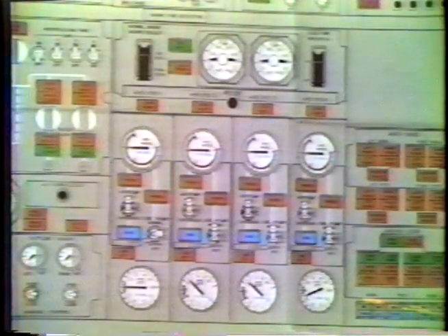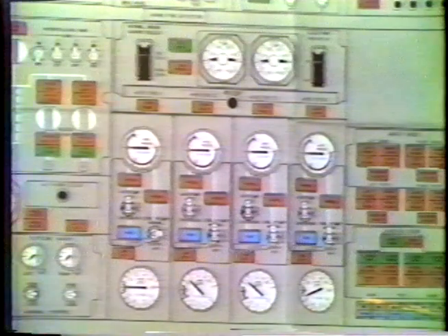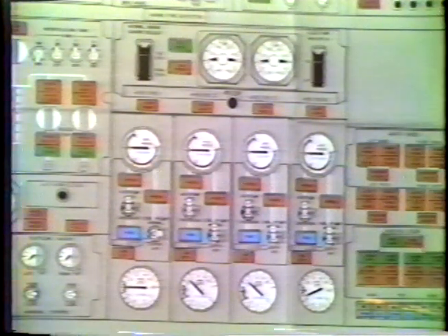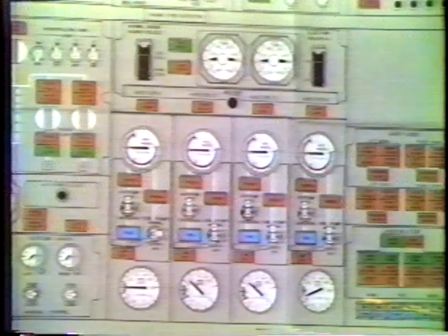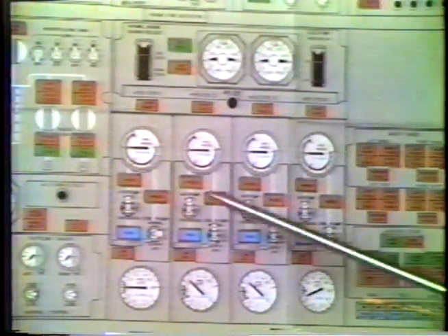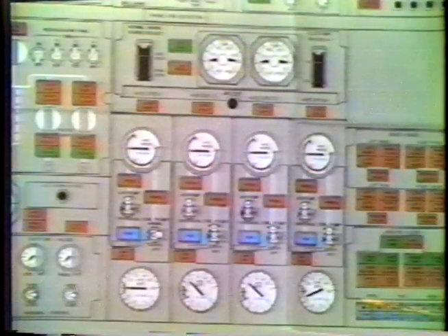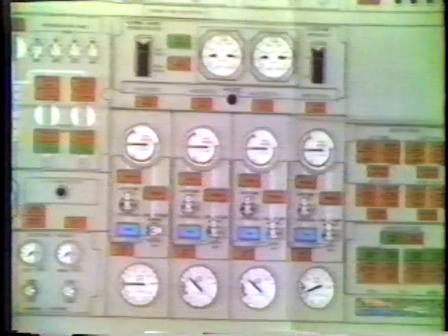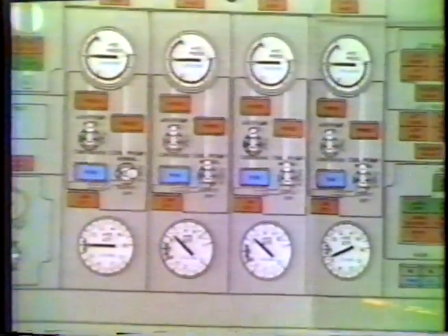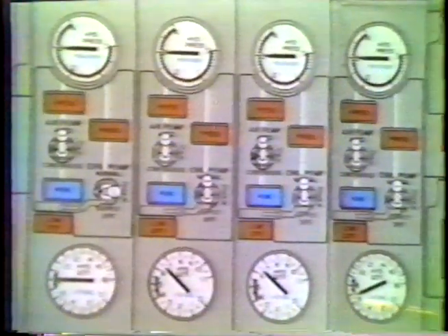A good way to remember what's exactly on each system is if you take the airplane and go right down the center of the airplane, the items on the center line of the airplane are generally on system 1. For example, the nose gear steering, the body gear steering, and the inboard trailing edge flaps.